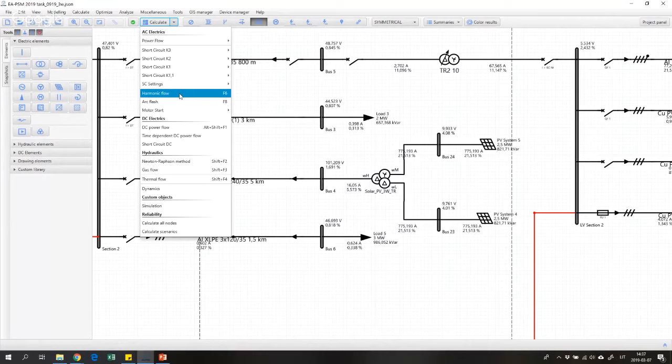And this kind of software is not limited to only these features. Actually, in industry, we can calculate something like arc flash, which is quite common. Motor starting, we have the capability to analyze dynamic motor starting, which again allows us to estimate how much time the motor will take to start, what the starting current will be, and all these things we can evaluate with variable frequency drives, with soft starters, so as to estimate various decisions on how to make this kind of process affect the network less.